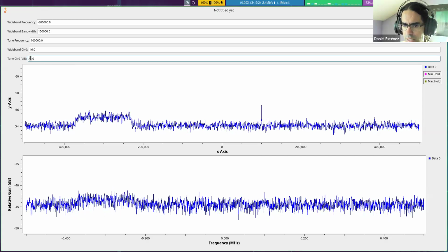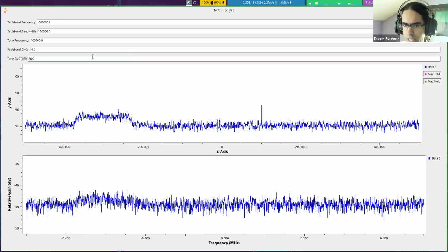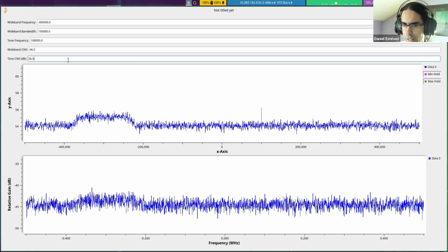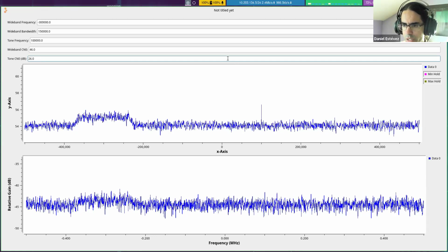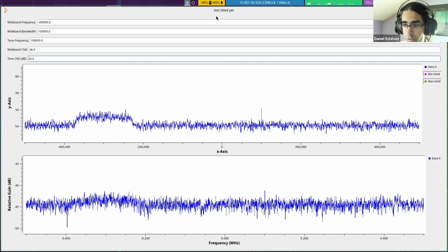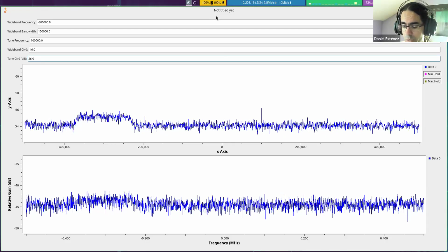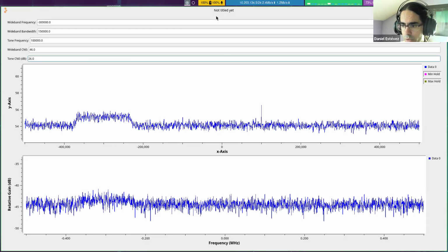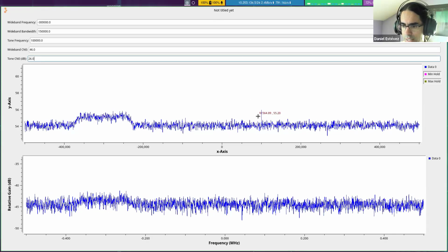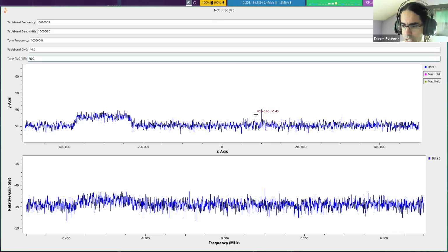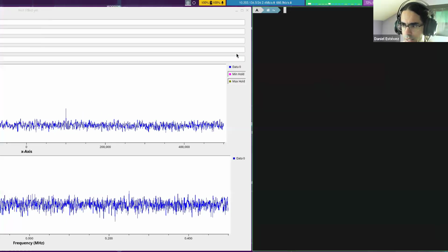What sets how weak of a signal we can detect? For narrowband signals, the calculation is fairly easy, at least to get a rule of thumb that will give you an approximation. The way to think about it is in terms of the FFT bin width. That's how much bandwidth each of the FFT points has.